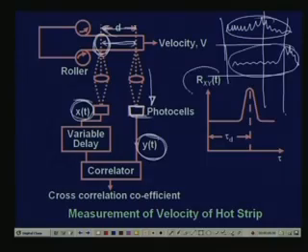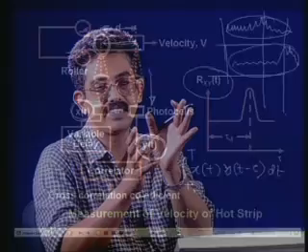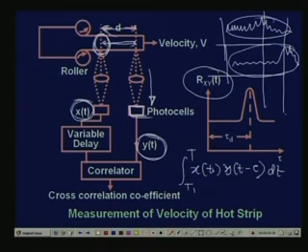If you have two roughly time shifted signals, they may be slightly different, then there is a technique of correlation. So, if we compute the integral from T1 to T2 of x(t) y(t minus tau) dt, we time shift one signal, multiply it with the other, and then integrate.